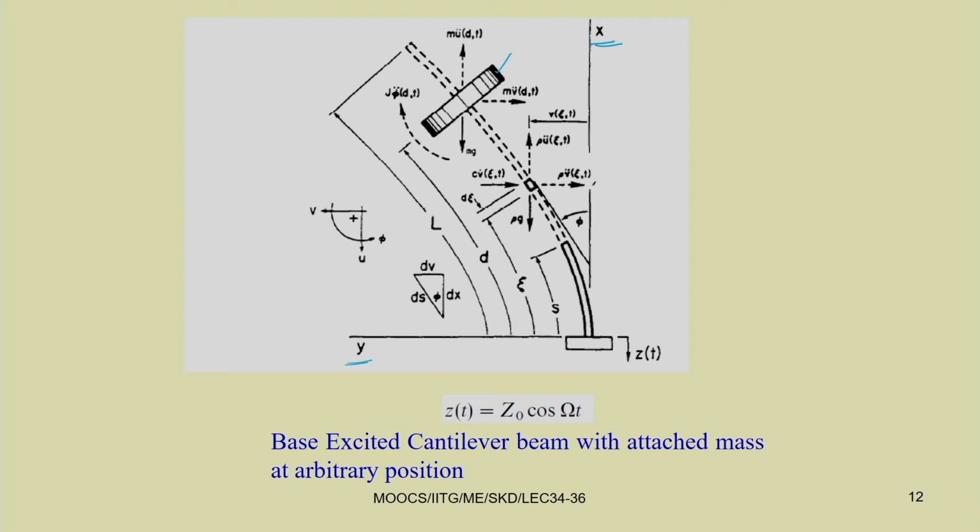So, you just see the body is moving towards left, as the body is moving towards left, the inertia force is acting towards right. The body is moving towards left and also downward, as the body is moving downward in longitudinal direction, the inertia force is in upward direction, m u double dot is in upward direction and m v double dot towards the right.